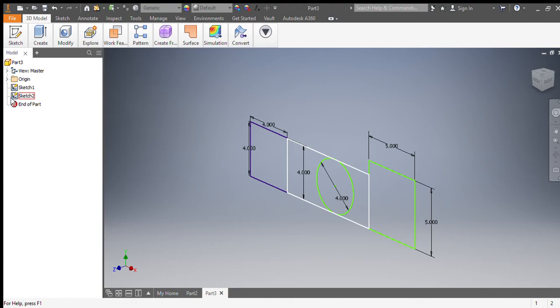Okay, so you have to make sure before you are done with the sketch, you don't start a new one. For example, when you guys start creating your linking cubes, you will notice that if you sketch everything first and extrude part of it, the rest of your sketches will be deleted. So, when you sketch part of it and you extrude it, then you can create a second sketch.